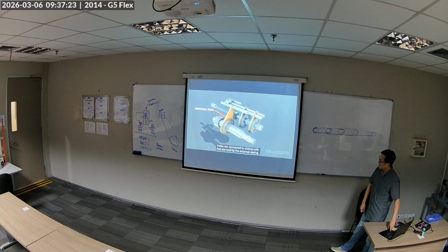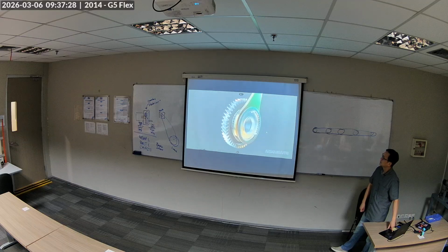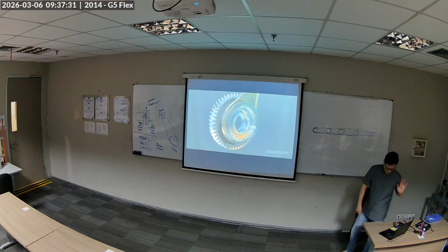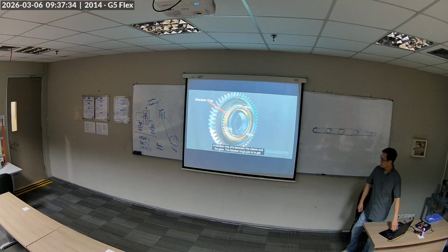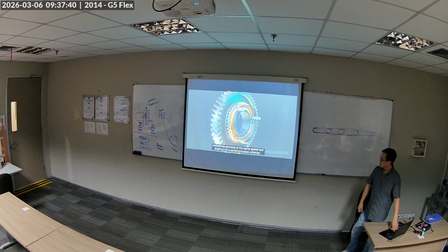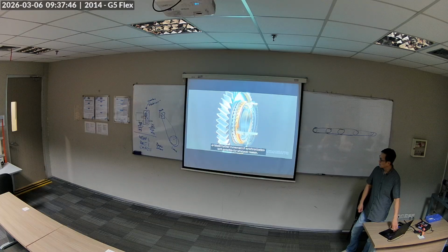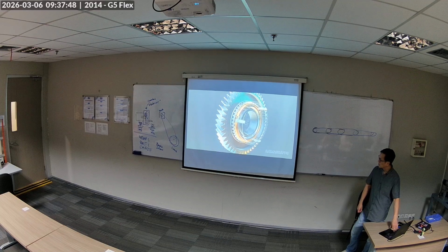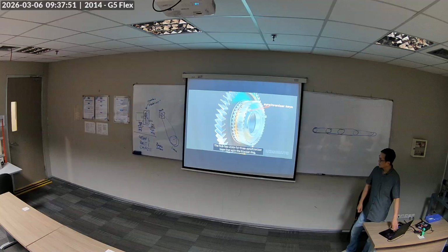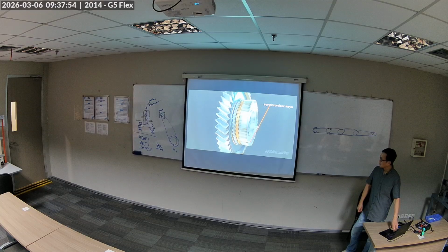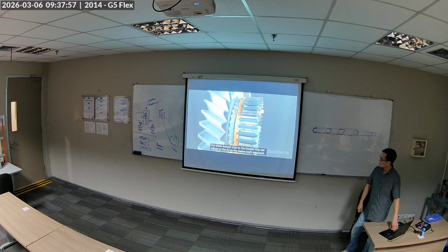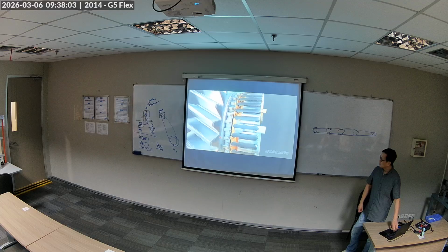Forks are connected to sliding rods that are held by the external casing. During gear selection, the fork moves the sleeve toward a gear. A blocker ring sits between the sleeve and the gear. The blocker ring's job is to get everything spinning at the same speed and lined up for a synchronization attempt, or block further movement if synchronization isn't possible for whatever reason. The hub has slots, or 3 synchronizer keys, that spin the blocker ring, but allow enough play so the blocker ring can adjust on the fly as the sleeve teeth approach.